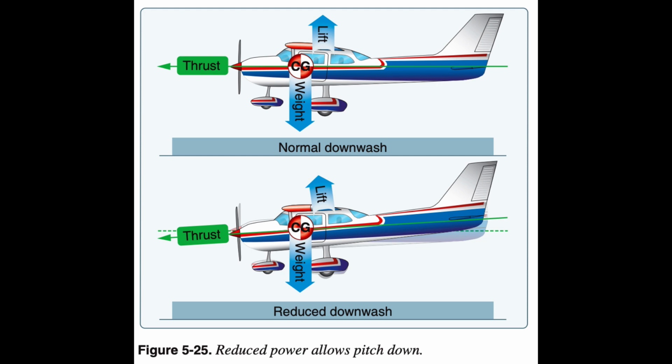As this climb continues, the airspeed again decreases, causing the downward force on the tail to decrease until the nose lowers once more. Because the aircraft is dynamically stable, the nose does not lower as far this time as it did before. The aircraft acquires enough speed in this more gradual dive to start it into another climb, but the climb is not as steep as the preceding one.